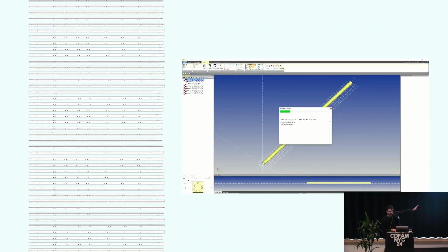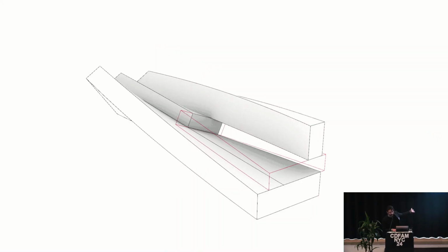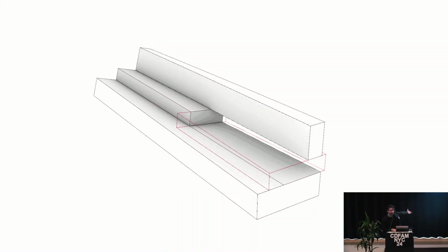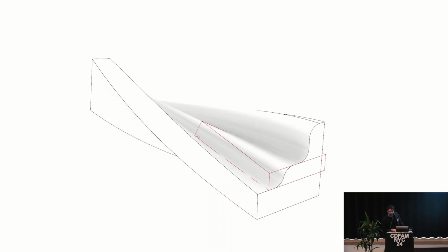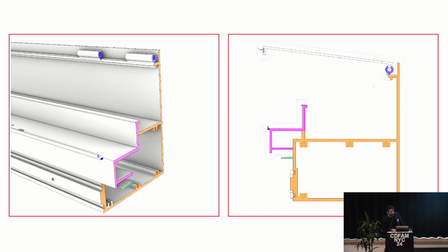That's actually a problem. So when you put this into CAM software to program the CNC machine, you're relying on its ability to detect the features. If you have all those artifacts, it's not going to work. The other problem is when you start adding twisting in here, the Boolean fails half the time. And then if you have twisting and fillets, it fails most of the time. So that's not going to work. So we invented this other way of working, which is to break this 2D profile down into individual regions that we can then tag with metadata.